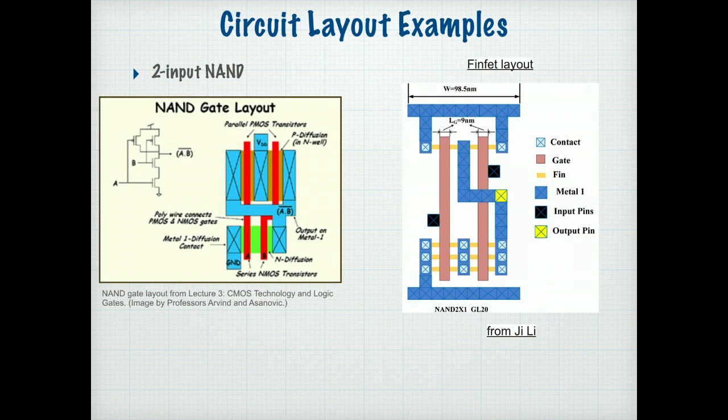This happens to be a NAND gate. A NAND gate has 2 N-type transistors in series, which are shown here in the schematic. And here in the layout, there's 1 N-type transistor, here's another N-type transistor. These are relatively wide. You can see they're fairly wide. That's to make this gate operate quickly, or have low delay, as we shall see.